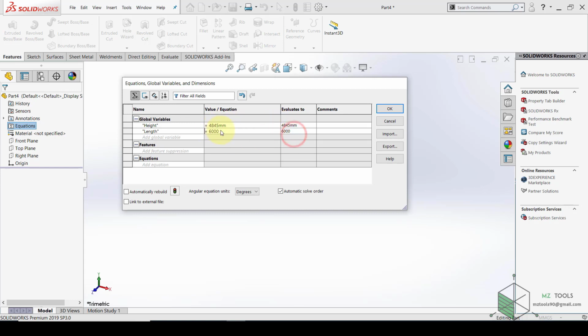If you don't have the millimeter listed here, once again click here and another click, you will have units, go down to millimeter, and now it's listed. Let's define an angle. Click here, and I want this to be 5 degrees, so go down to units and select degrees.